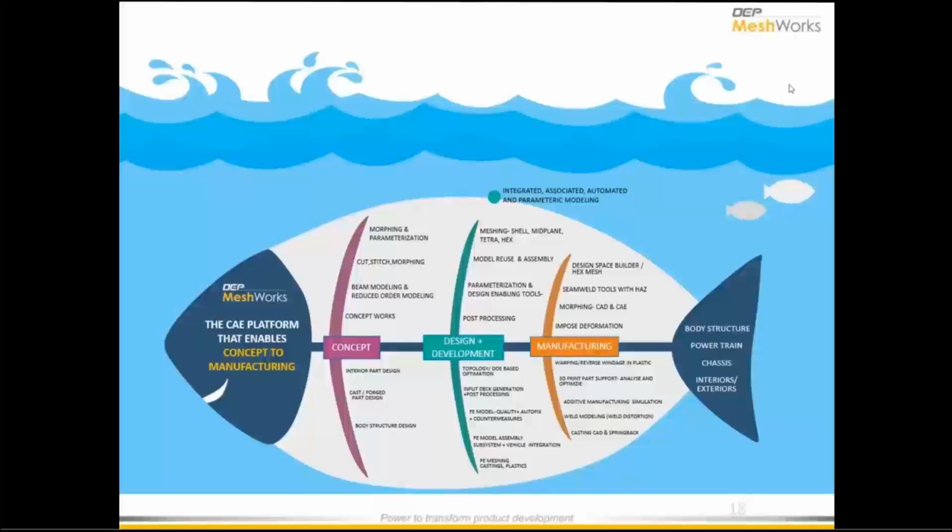And where it really scores on hex meshing and capturing different geometries that you see in the battery as well as on the motor is the extruded hex meshing, where we are able to capture all the features, take them to a plane, mesh them, and actually extrude them. We are going to demonstrate that in detail in one of the upcoming webinars. Stay tuned, and that will answer your question on hex meshing. Certainly the process is more efficient. It saves you close to 50% of the time in certain complicated components to generate a hex mesh, if you're looking for that.